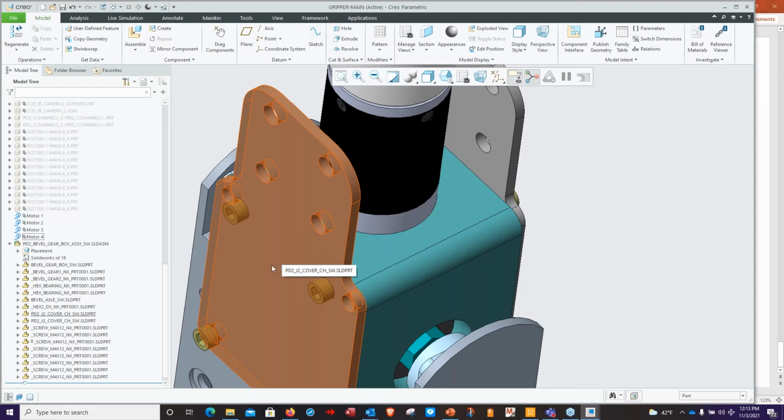So any change that you have to do, you can reflect some of those through the flex modeling and relay that back to the designer that's working in SolidWorks. Then they will have a reference model to use to modify or change those. But it would be recommended, if SolidWorks is the control CAD program for those components, that the designer in SolidWorks should update that accordingly.